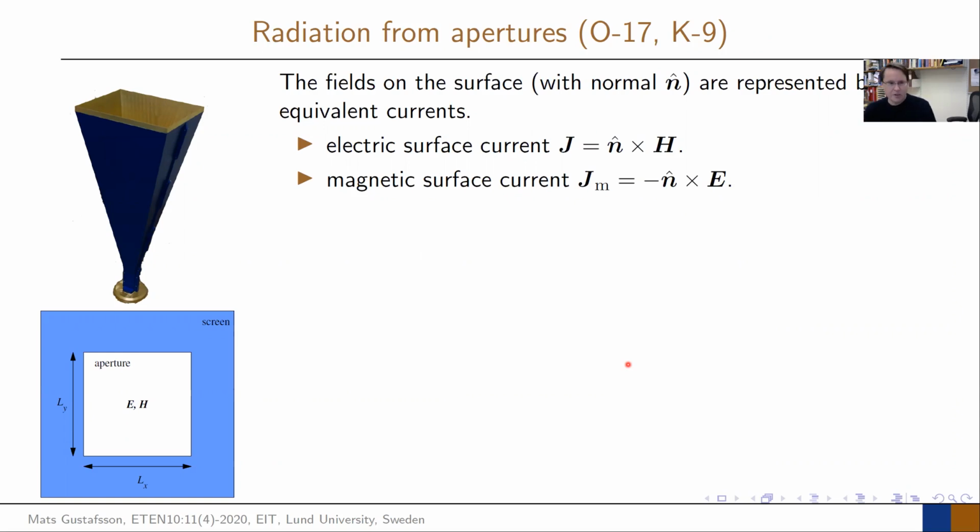And if you think back at your first favorite antenna, your dipole, and of course your patch afterwards, when we determined the radiation pattern from this, we said that the radiation comes from the current that we induce on the structure here. So in this case, we have a real electrical current flowing, we have charges that are accelerated, and that acceleration causes this electromagnetic field to radiate.